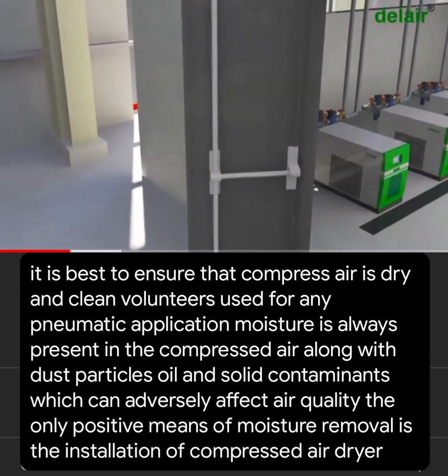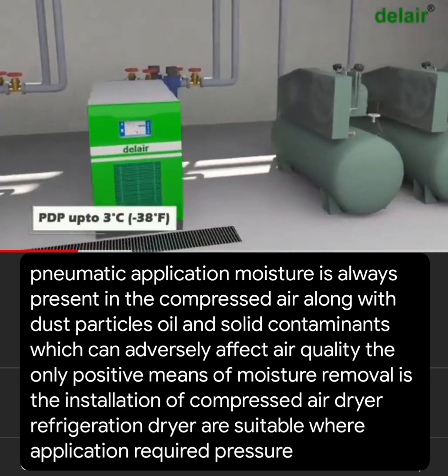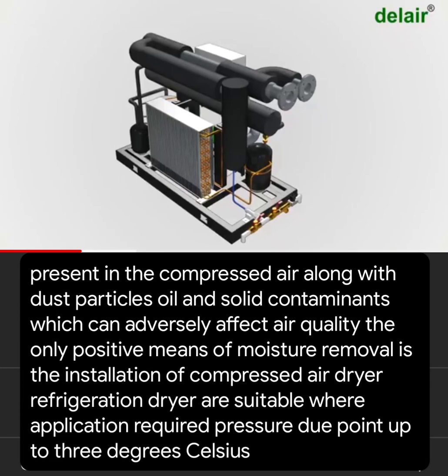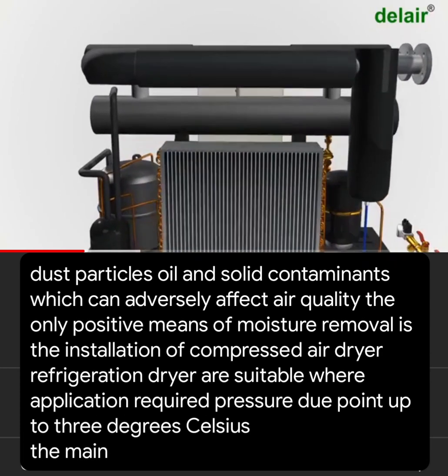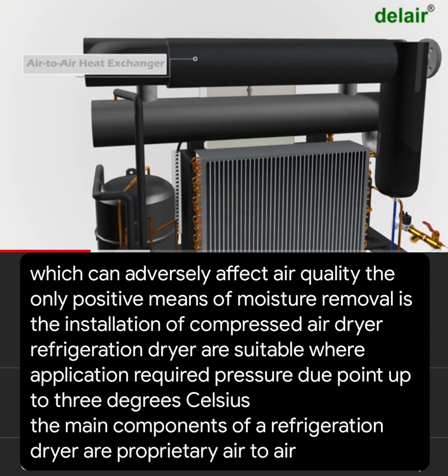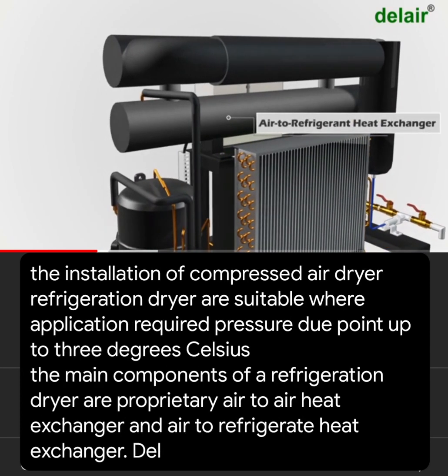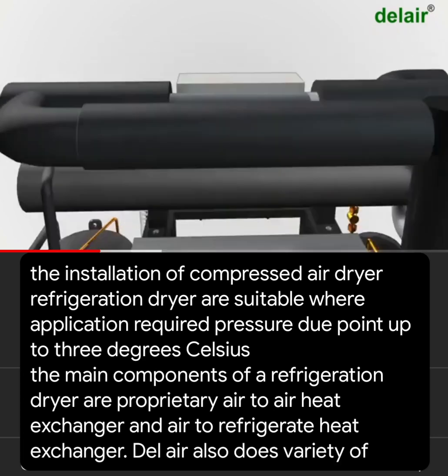Refrigeration dryers are suitable where applications require a pressure dew point up to 3 degrees Celsius. The main components of a refrigeration dryer are a proprietary air-to-air heat exchanger and an air-to-refrigerant heat exchanger. Dell Air also does a variety of advanced heat exchangers.